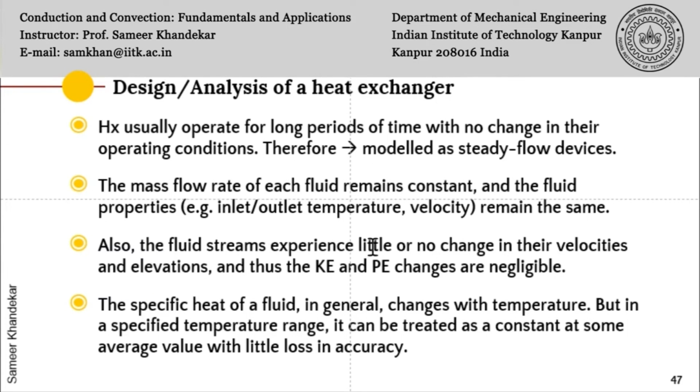Then the fluid streams experience little or no change in their velocities and elevations, and thus the kinetic energy and potential energy changes are also negligible. So this is also a common assumption under which we will do the following analysis. Then the thermophysical properties like specific heat of the fluid in general change with temperature. We all know that. However, sometimes the temperature change may be large, but for a given range, it can be treated as constant at some average value with little loss of accuracy. So for most analysis, we will assume that the thermophysical properties are constant.